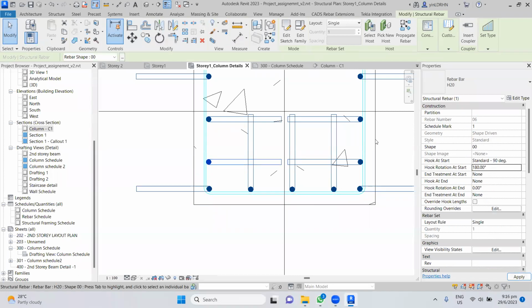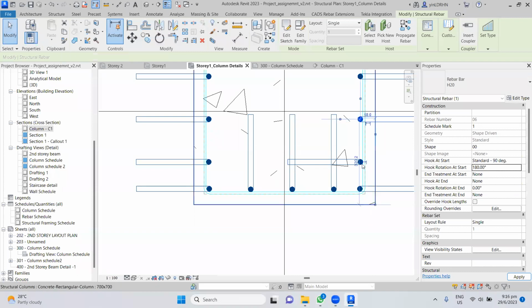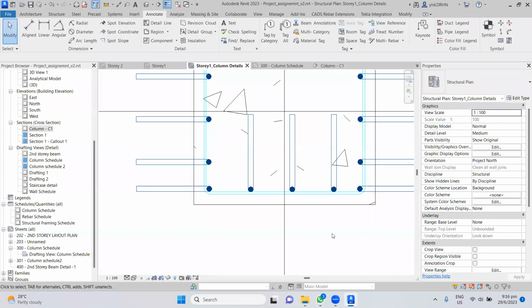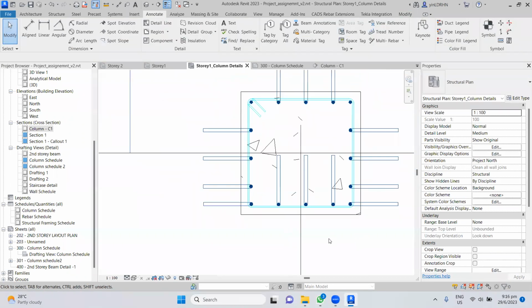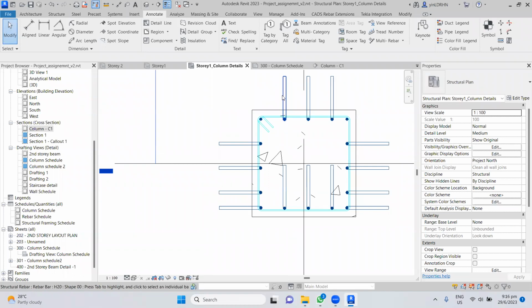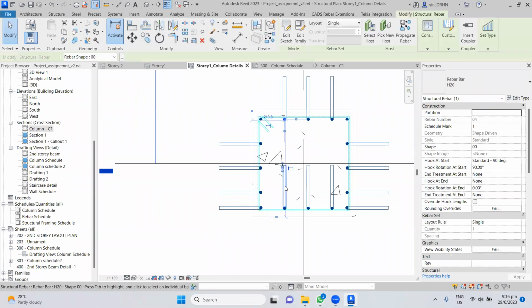So it's just detailing. Based on your own arrangement, you have to set up. The purpose of 3D rebar is this one, right? You can make sure that your rebar can be anchored properly before going to construction, right? If you don't want this kind of detail, then no need to develop this, because it is actually time wasting. It's taking a lot of time to do it, right? If you're not going to use it, what's the purpose?